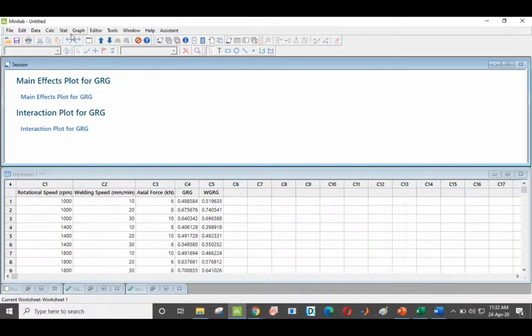Now, Anova. We have to formulate Anova. Someone asked in the morning, sir, we have determined the highest influential parameter from the main effects plot itself, then why are we going with the Anova table? Only from the Anova table, the variance that exists between 2 parameters can be studied, and the percentage contribution of each and every parameter can be determined.